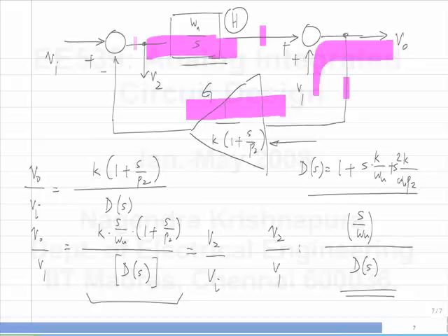So similarly, if you look at the transfer function between Vi and V0, at low frequencies there is active feedback, but at very high frequencies the feedback is kind of broken. So it simply goes through omega u by s. Okay, so that's what you expect. And at very high frequencies, of course, it becomes 0. So this is a low pass kind of function, or low pass with a 0. This is high pass, this is band pass, and you can get all kinds of exotic combinations.